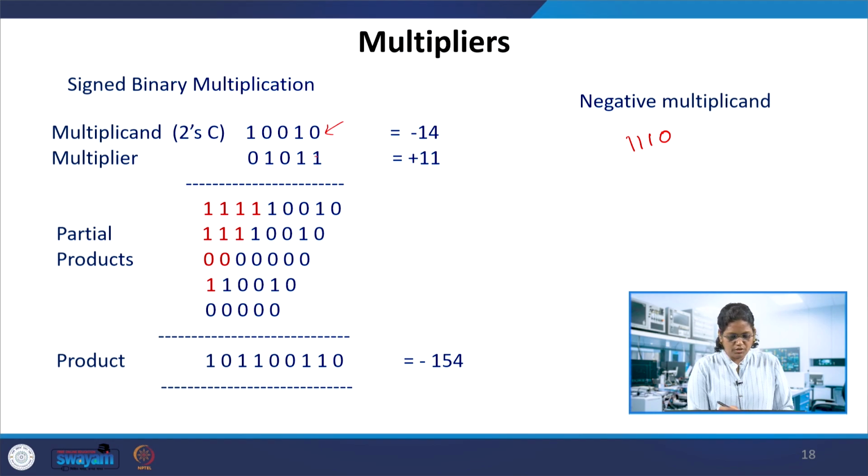With this, the first thing is this multiplicand: because we multiply by 1, it is copied, 10010, and extend the sign 11. This is a negative number now being multiplied, so it needs to be extended 111. Similarly, the next multiplicand with sign extension 0, and the last one, which has 01001.